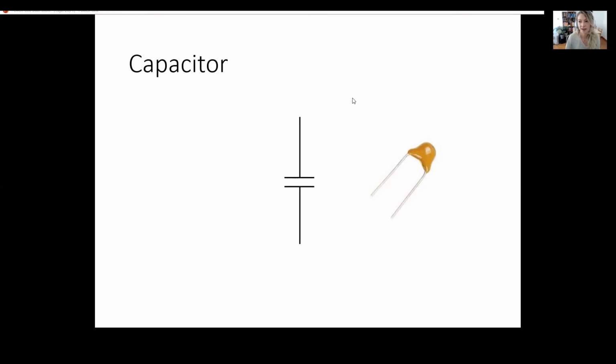All right, so our capacitor can separate charge. The amount of charge Q that the capacitor can separate depends on two things. First of all, the capacitance of the capacitor, which is an intrinsic value that depends on its size. The bigger the two plates of the capacitor are, the more space it has to separate charges. It also depends on how close they are together. The closer they are, the more the forces will be able to act on each other and the higher the capacitance will be.